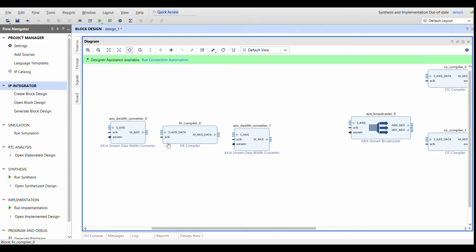This is the FIR filter. This is going to take IQ samples from your SDR application such as HPSDR. So 16-bit I and Q input, and it's going to interpolate the data from 48 kilohertz to 384 kilohertz, so a factor of 8. FIR filters are quite an expensive resource. They have a lot of multipliers, so we're going to do something slightly clever and reuse that filter. So we'll use the same filter for each of I and Q.